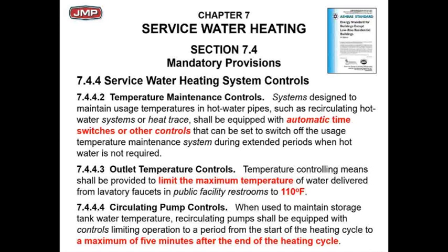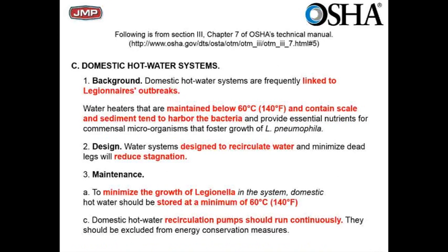And I think you need to keep that in mind when you look at the next slide. This is OSHA. What does OSHA say? It just kind of got you in a box. I think the most important thing to get from this particular slide is OSHA is worried about Legionella, and we know it can thrive in hot water systems. They don't want any dead legs or any areas you don't have recirculation through. Down under maintenance, section 3, they want you to get that water to roughly 140 degrees to kill it.